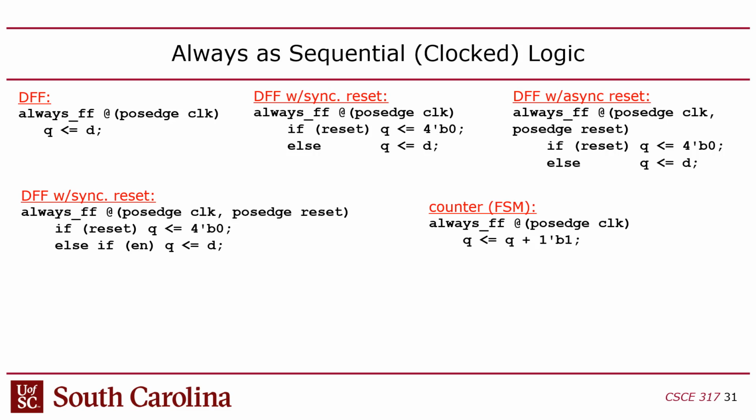Any questions about that? Does that make sense? So this is how we would build, for example, an SPI channel in hardware. We'd have to have clocked logic, right? Because there's a clock in there. Same thing with I2C or UART. Anything that changes its behavior over time needs a clocked circuit, sequential logic. Okay, now there's some variations you can do here.